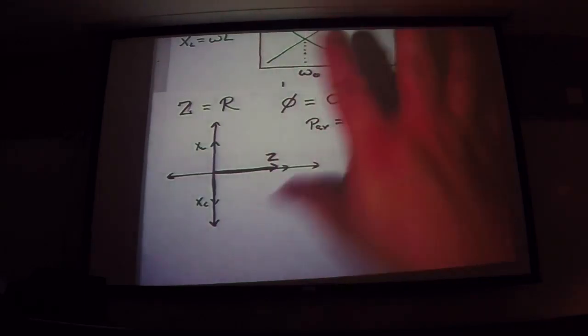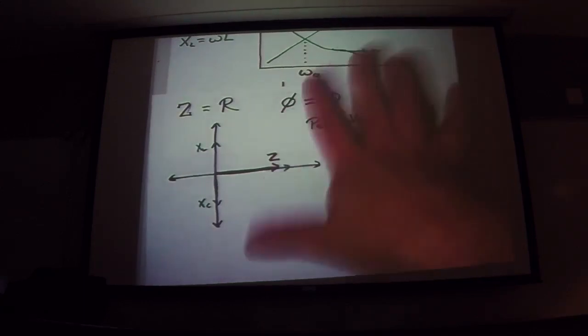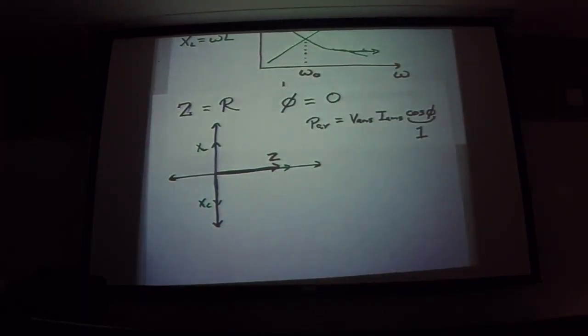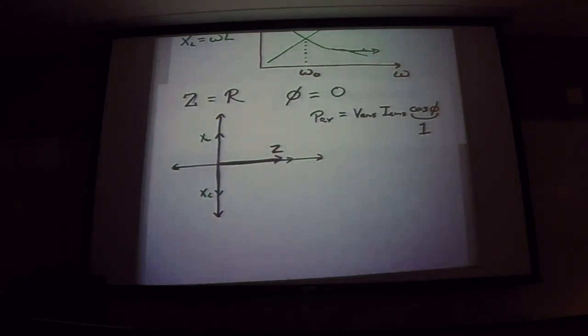So this is going to show you the power of an RLC circuit. And here's why. Because we can now have them adjustable so that we can actually allow a particular frequency of current to go through and pretty much block everything else. And depending on the value of your resistor compared to your other circuit elements, that determines how tightly you want that window to be where you're getting close to that resonance. There's a nice graph in your text, so I'm going to switch over there.